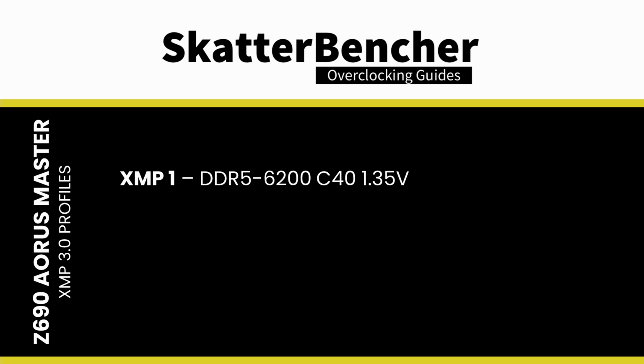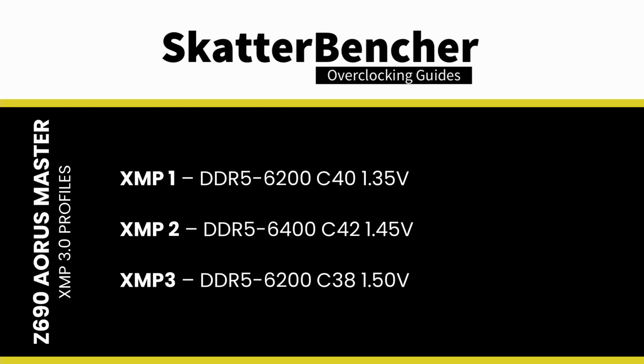For each of the 3 sub-strategies, we'll also be using one of the 3 available XMP profiles. The profiles are XMP1 DDR5-6200 40-40-40-80 at 1.35 volt, XMP2 DDR5-6400 42-42-42-84 at 1.45 volt, XMP3 DDR5-6200 38-38-38-76 at 1.50 volt. For strategy 2A, we use the Enhanced Multi-Core Performance Profile and the first XMP profile.